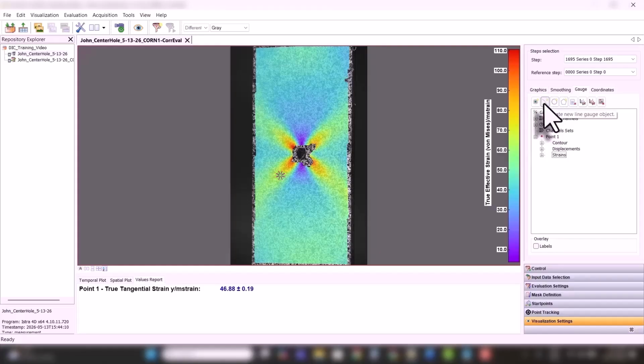Okay, you could do a line. So you just left click, and then to close out a point or an object or a shape like a line or a polygon, the final point you add, you want to right click, and that closes it out. That'll add the line, finish it and add the line. So here, what's the length of the line?